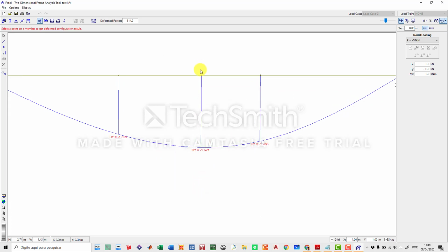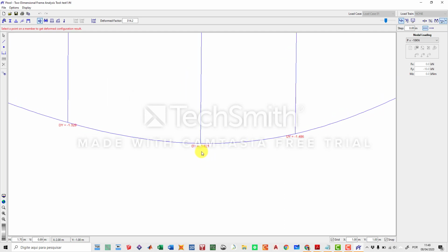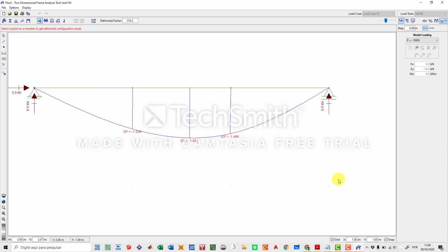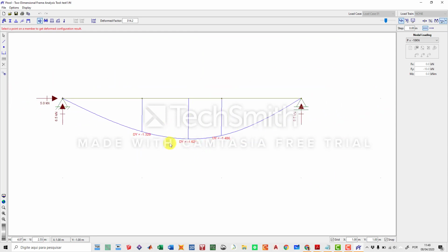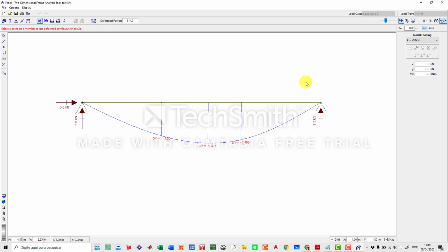All right, so here in the center of your beam, you have the maximum displacement of 1.6 millimeters. That displacement for a 3 meter beam span is really great. So probably the previous section that we have chosen was really adequate for the loading conditions. Okay, so this is one example of how you can assess structures and do the pre-design phase.